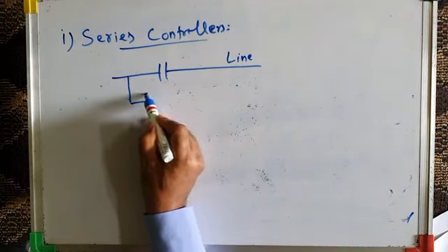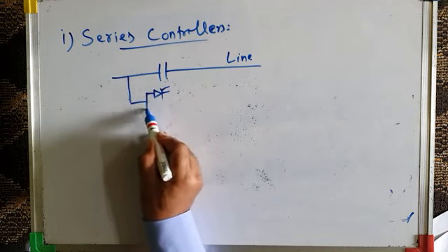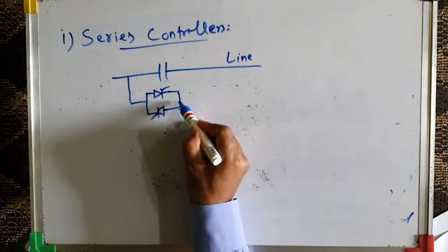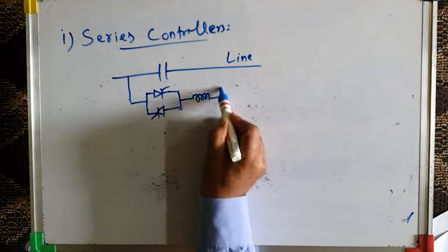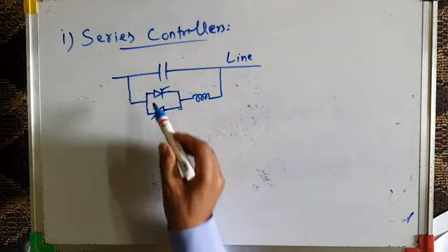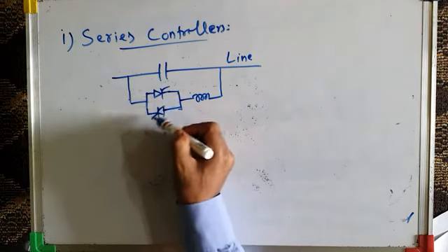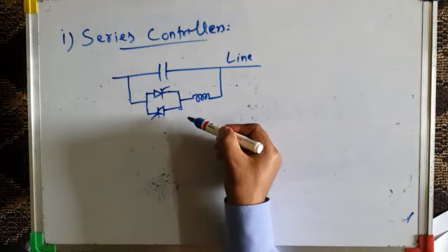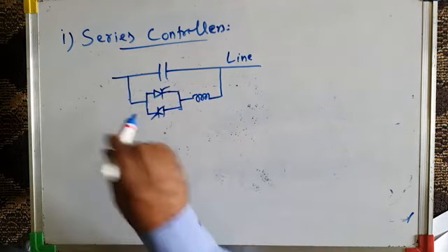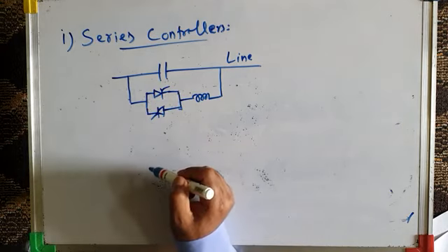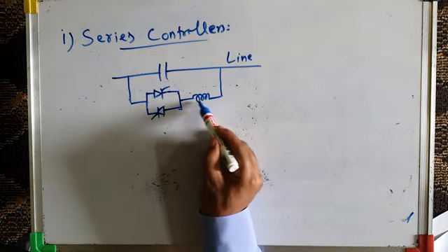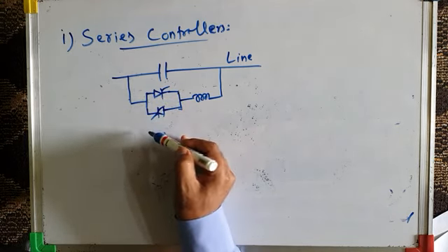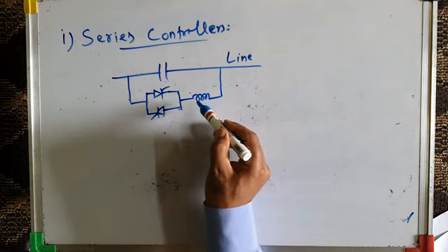Then I make it a variable capacitance with the help of anti-parallel connected thyristors like this. These are SCRs, and they are connected in series with the inductance. When voltage is positive, this thyristor is on, and when voltage is negative, this thyristor is on. So it is a bidirectional thyristor based switch. By delay angle or firing angle control of this switch, the inductance varies.